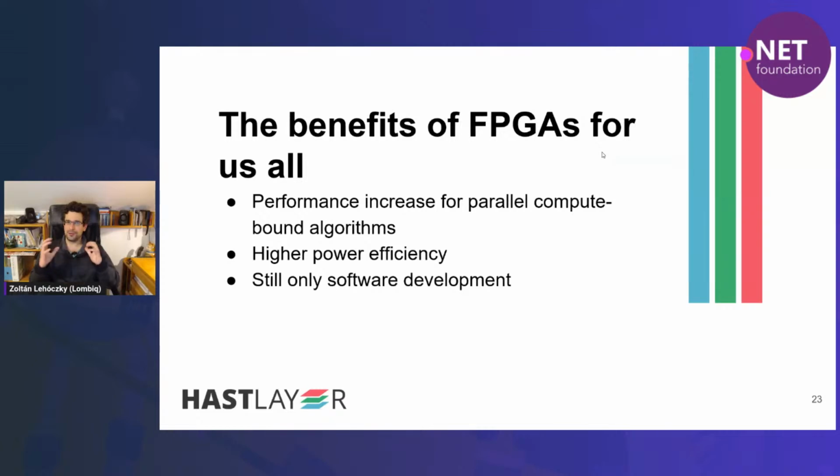Now, to summarize this, why you would use FPGAs is to get the performance benefits of them when you have some highly parallelized, compute-bound and/or memory-bound algorithm, because then FPGAs can provide you with a substantial performance increase. I will also show you an example of that. At the same time, you can get a higher power efficiency, so your software will consume less power.